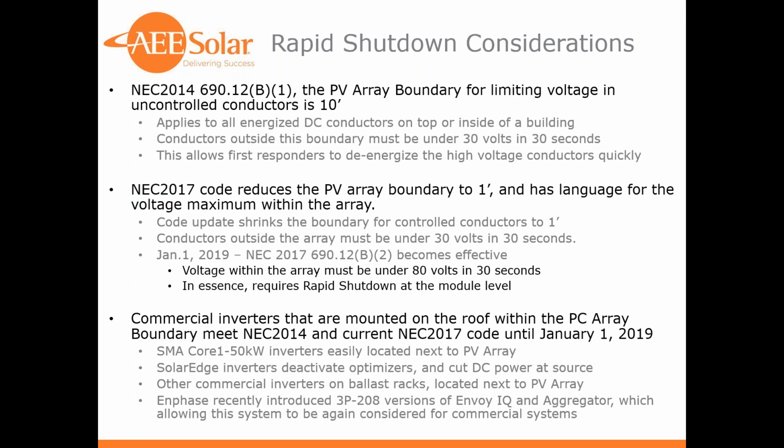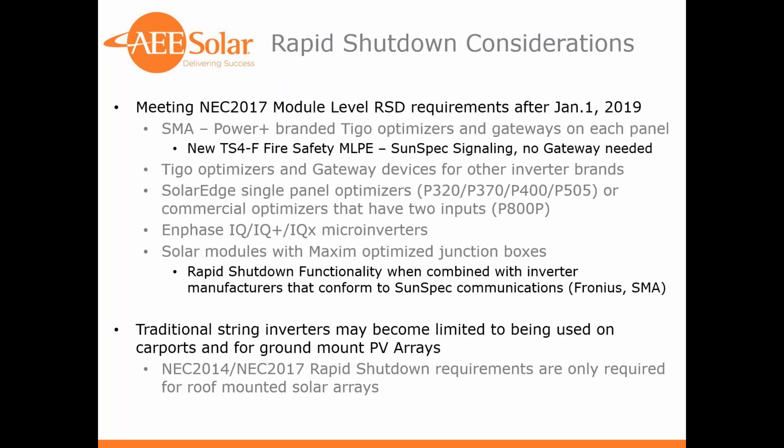So after January 1st, what do we do? SMA has partnered with Tigo and has branded their optimizers and gateways to be used on both residential and commercial systems. We haven't seen a lot of detail on this yet, but Tigo has their TS4-F fire safety MLPE in addition to their other Power Plus optimizers. And the advantage there is that since it is signaling over SunSpec, we don't require the gateway and the Cloud Connect. And this is strictly a fire safety rapid shutdown